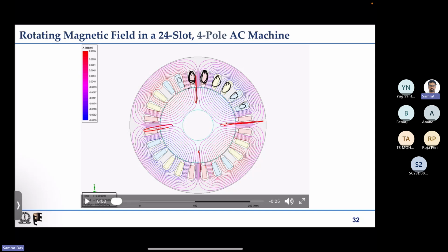Actually, the bar case that we have seen is very close to that. Here, what is the constraint? Here we are putting two coils of R phase, because these two coils are connected in series. So whatever current one conducts, the current in the other also has to be the same. But the beauty about bars is there is no such constraint. This one can have its own independent current, and this one can have its own independent current. I am talking about two subsequent positions.